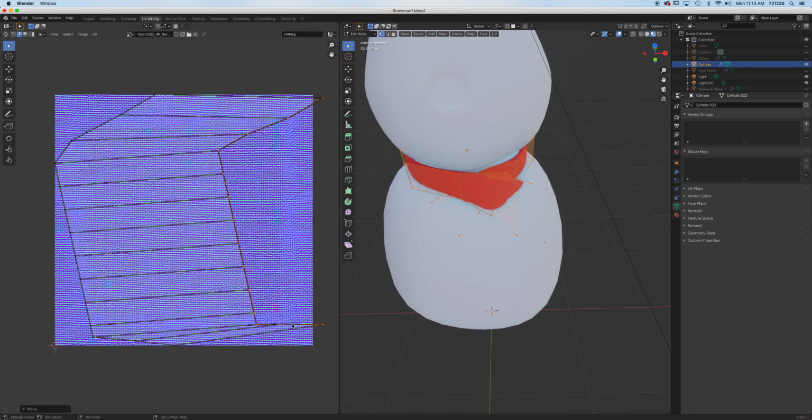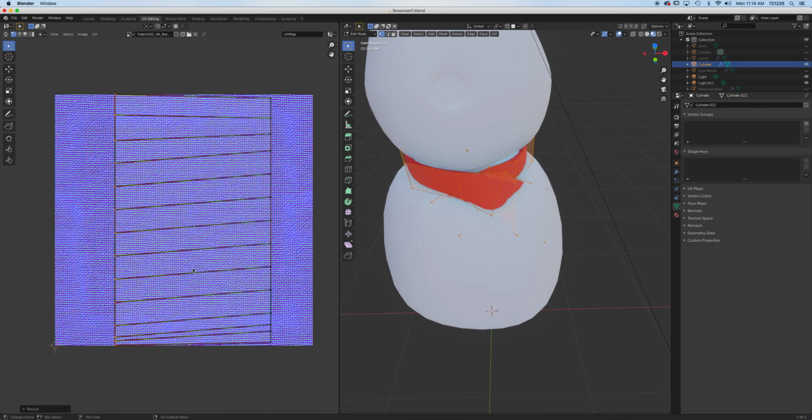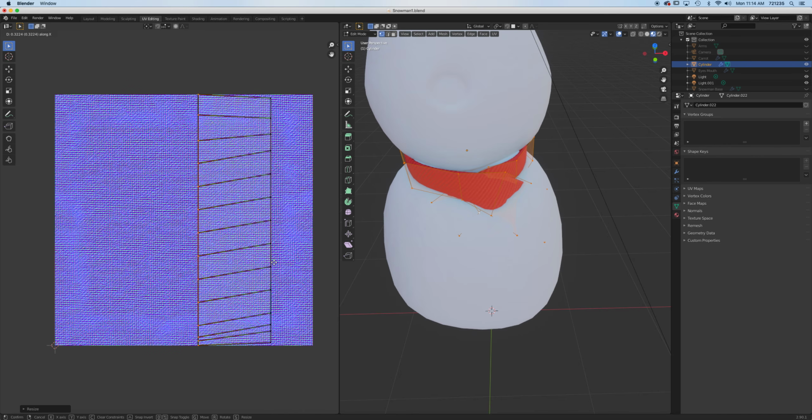This one I have to manually lower here because otherwise it'll scale it and look all flat. So here we go, and that's probably fine right there. I can just select all those points, x-axis 0, straight. And we'll go right here. Let me turn on screencast here so we can see, oh, I don't have it showing there, but S, X, axis 0. Then we can make this G, X, like so.